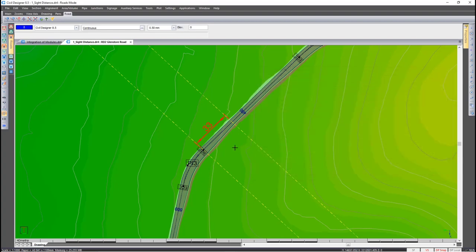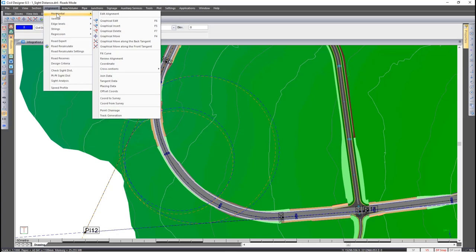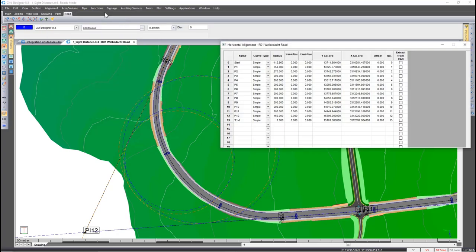Looking at compound curves, many of our clients utilize compound curves at on and off ramps. They use these compound curves to slow the vehicle down somewhat before implementing a sharper curve. Selecting our active road to show you we are working with HPI 12. I have beforehand put in geometry entities for explanation purposes. Eventually our HPI will be closer to these geometry circles. Taking a look at the existing horizontal curves, HPI 12 has a simple curve radius of 150.